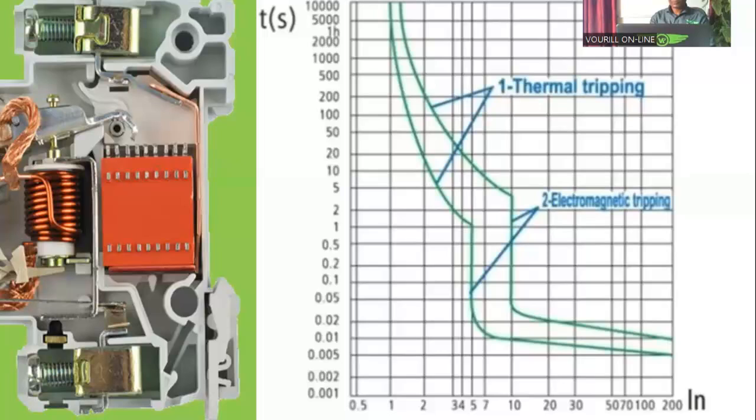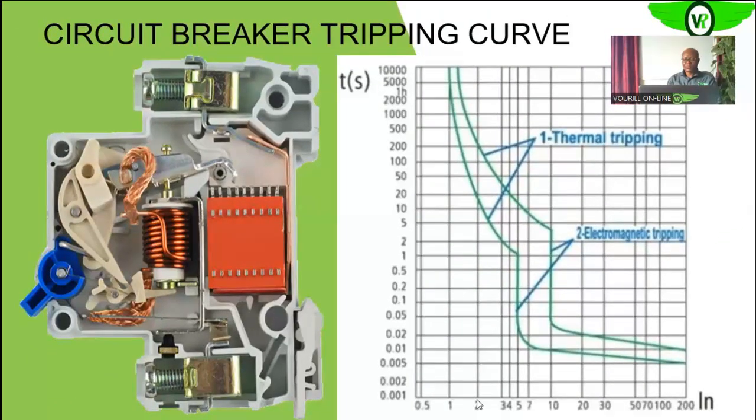And that will mean that for the same amount of current, you need more time for it to get heated up. So if we still look at the 2 times the rated current rating, you see that you require approximately 200 seconds to cause the trip of this particular circuit breaker when it is cold.